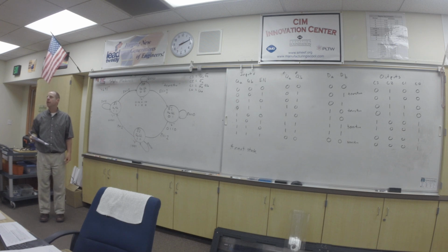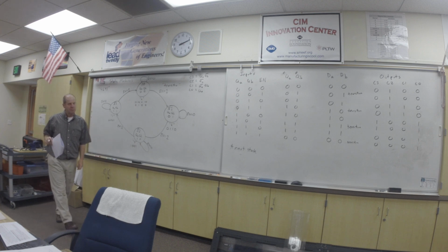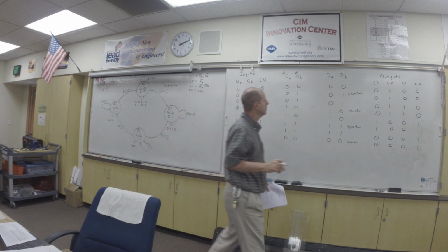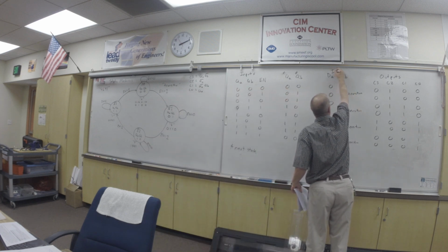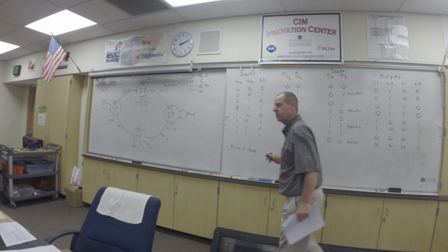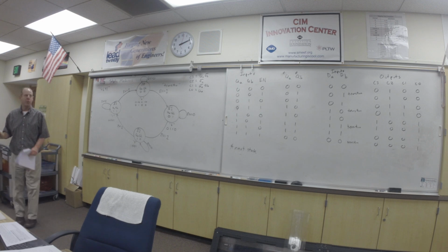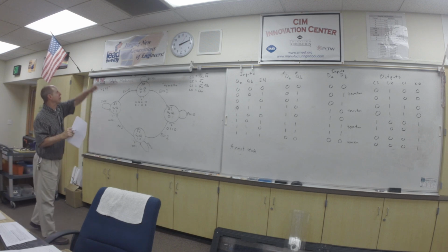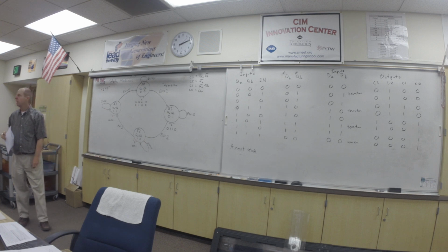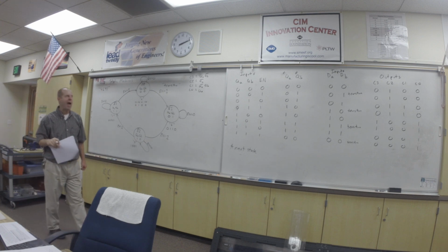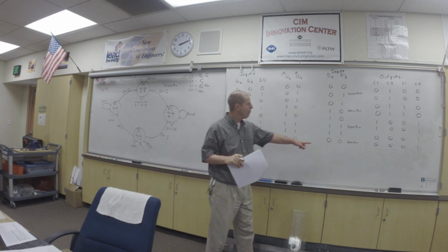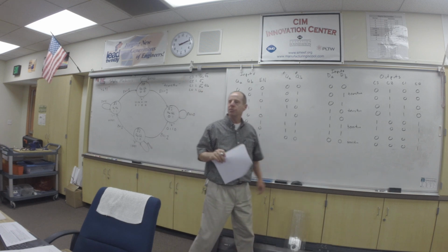So where do those come from? They come from the flip-flops. I'll draw you a picture in just a second that will help you to understand and to see where these are coming from. One other thing: DA and DB are inputs. Remember? D is an input. So the QA and the QB and the enable have to loop around and come into the DA and the DB. So we need to do the same thing for that. We actually need to do a K-map, and we need to simplify what's going to go into these. I've already done that.